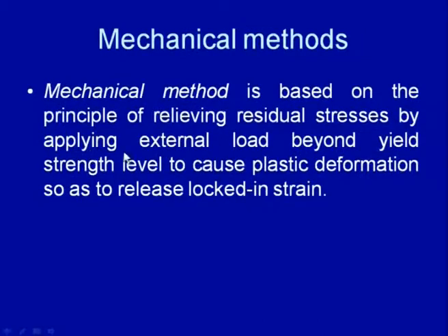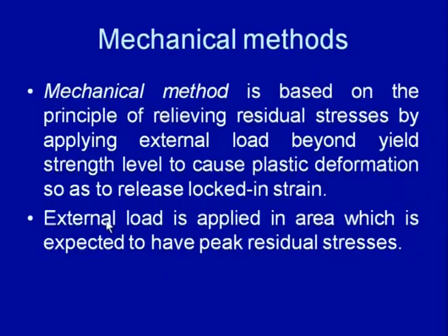The mechanical method is based on the principle of relieving residual stresses by applying an external load beyond the yield strength level, so as to cause plastic deformation in order to release the locked in strain. In the mechanical methods, mainly we try to apply forces in the area where locked in strain is present, so as to cause plastic deformation, and the plastic deformation releases the residual strain which is locked in, and the release of the locked in strain relieves the residual stresses. For this purpose, external load is applied in the area which is expected to have the peak stresses.